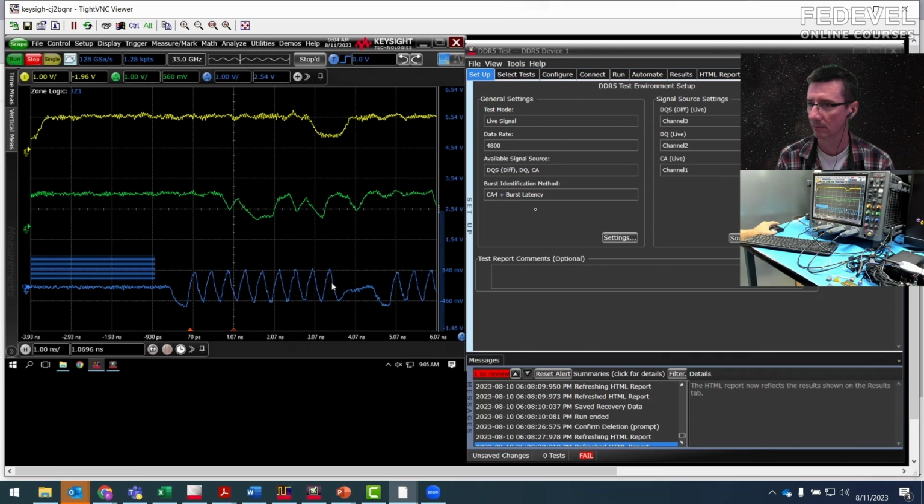until the very end. Notice that this goes high impedance. And finally, this is high impedance as well for a short time. This always pulls up high. So during the idle state, this is pulled up high here. And then we have to hold this last part. This is called the post-amble, right? So this is the last latching edge. This goes high, it's done. And then finally, a half a cycle later, this goes high impedance. And then this turns on, and then now we have our data starting up again.